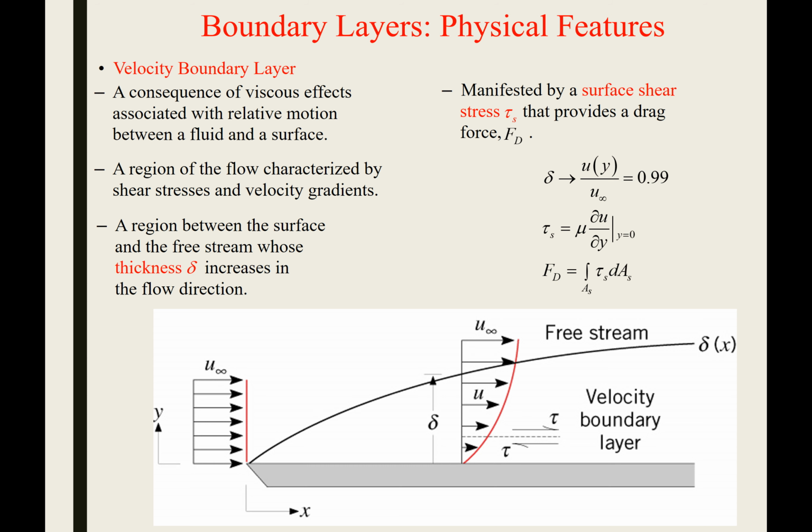And so in terms of velocity, we'll start to see the formation of a velocity boundary layer. Just back to the wind example, if you were to put your hand directly on the table, you wouldn't feel as much velocity in the wind as if you put your hand up here. You could probably do that just by visual and tangible inspection. You would experience a higher velocity further away from the table because of this formation of a boundary layer.